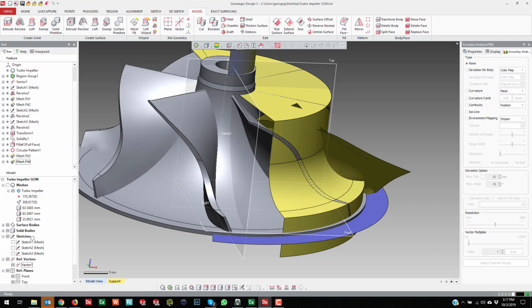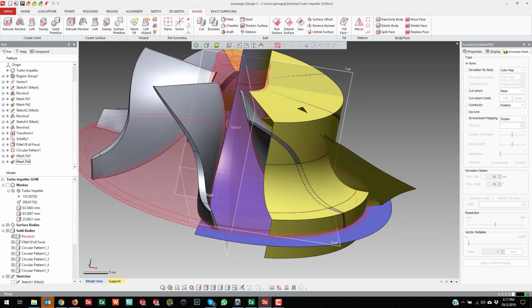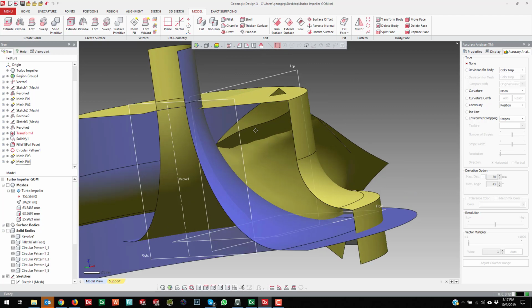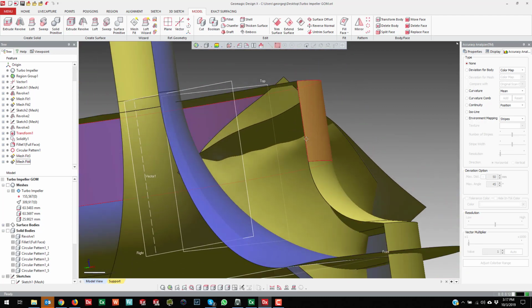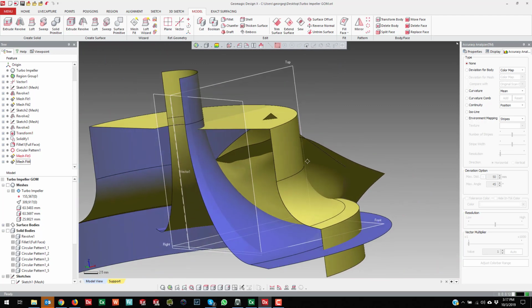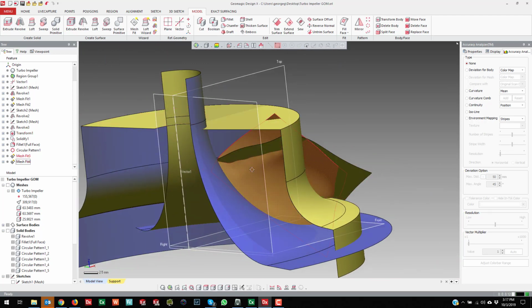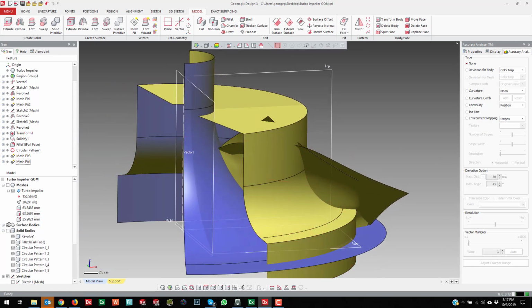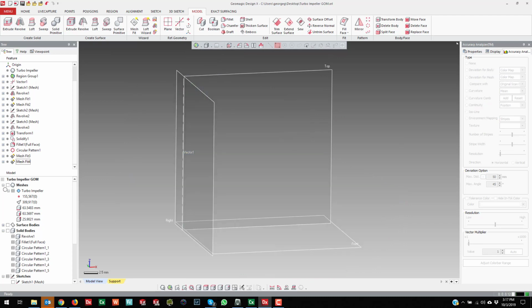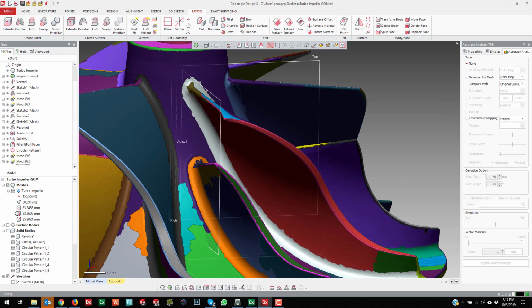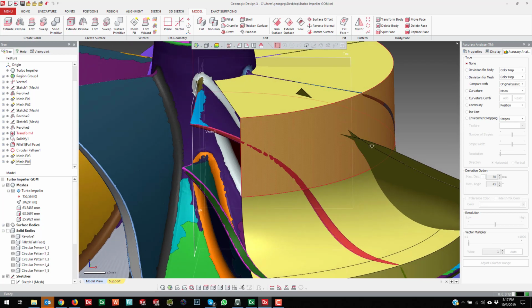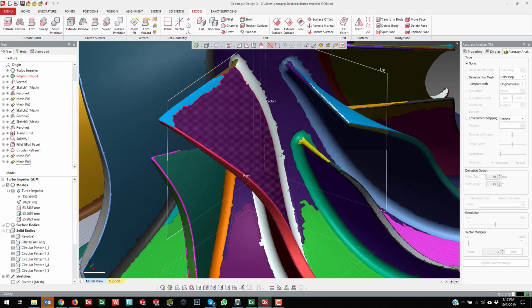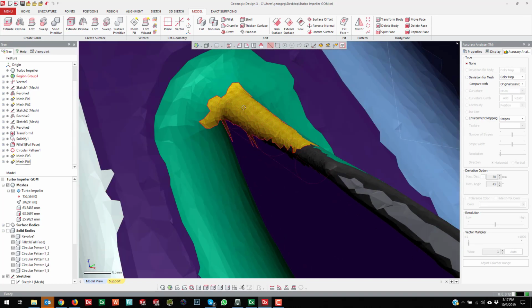Now let's just turn off my other solids right now, the revolve and actually just everything, all of them. One problem I have here is this one is a little bit different, right? Because the top surface here is different from the top there. So one thing that we did before on this type of model is I went ahead for the small one. Let me just double check and make sure I got the right one. This one right here. I came in and I just made a region and I did a surface trim on it.